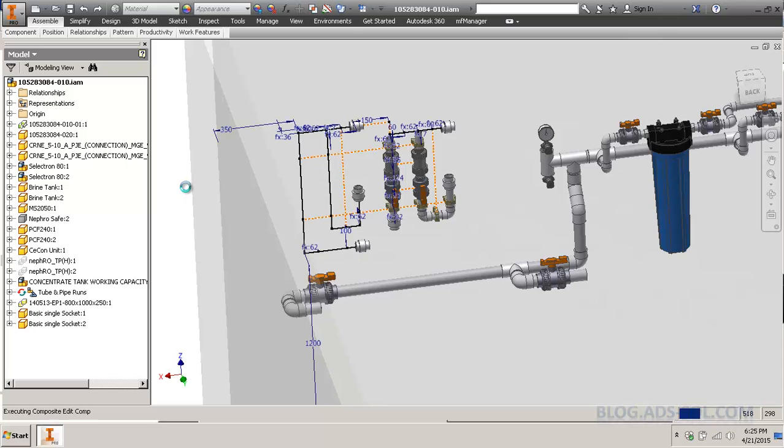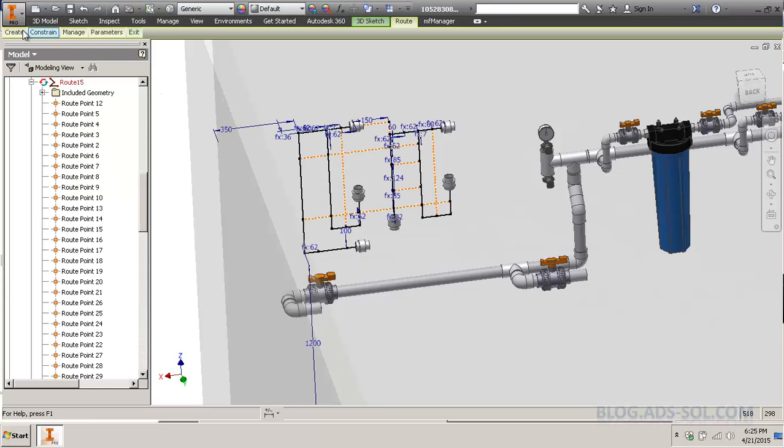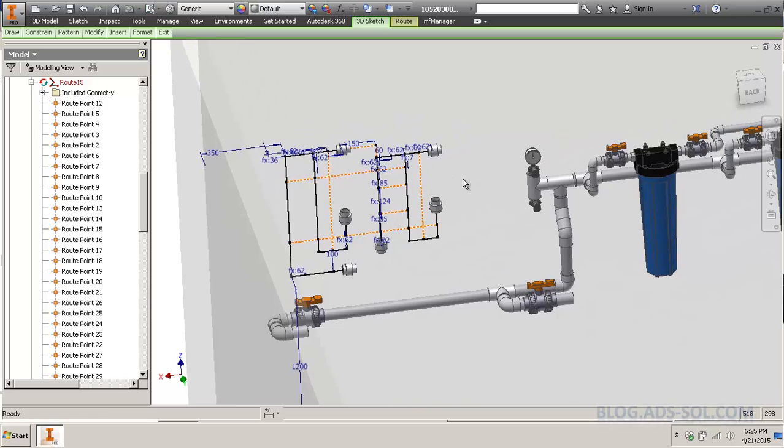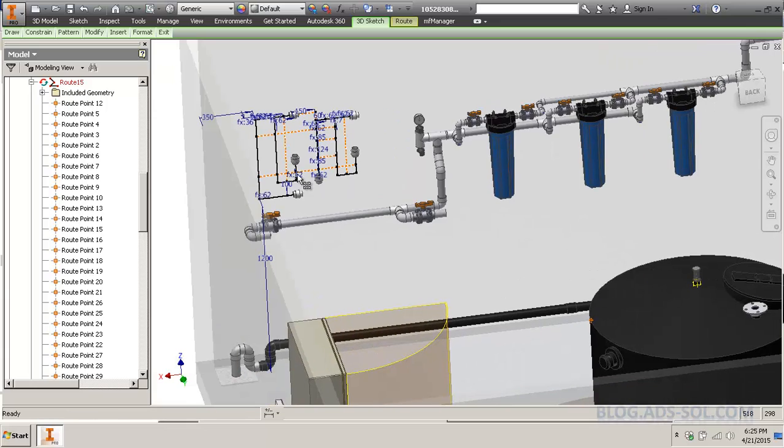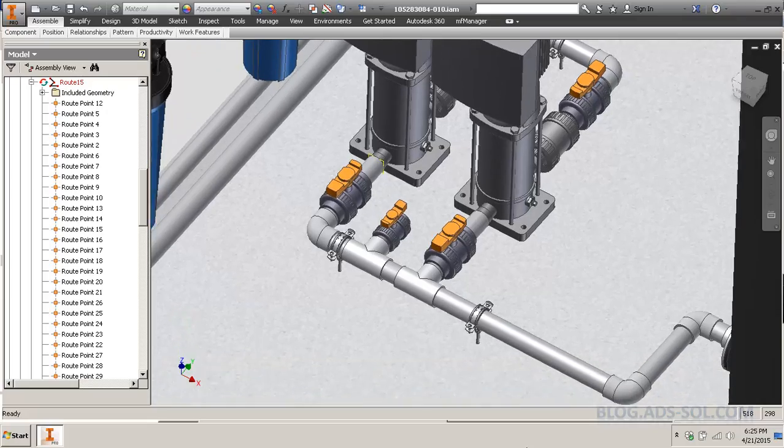Right. So construction lines cannot be drawn with a command, even if you go in the 3D sketch, and if you select a line, you cannot change it to construction or vice versa. But you can still draw construction lines and help out with designing your roots.